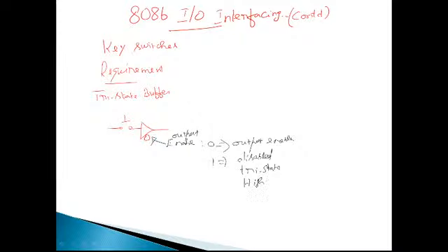Being electronics students, you should be able to understand this high impedance state. That is, the output line is logically disconnected from this particular circuitry. The data bus of any microprocessor based system is a shared, common one. At any given instant of time, the microprocessor will be able to communicate with only one selected device.